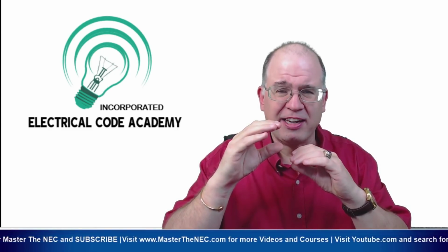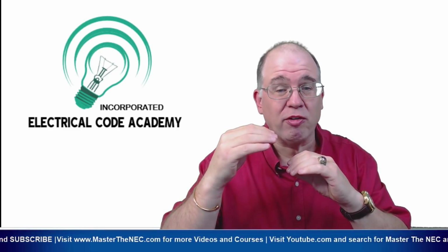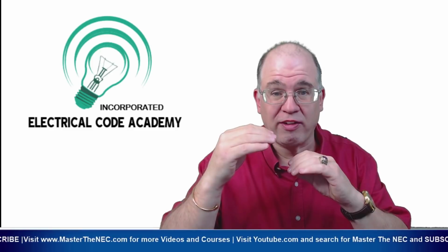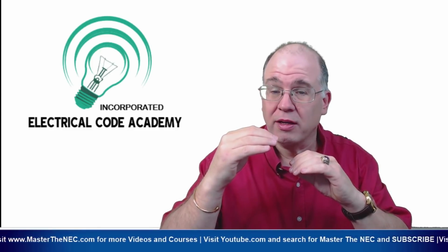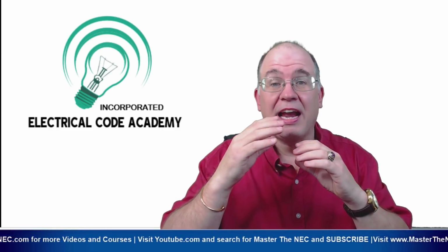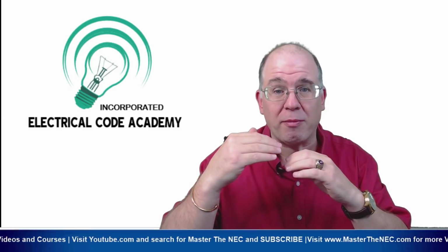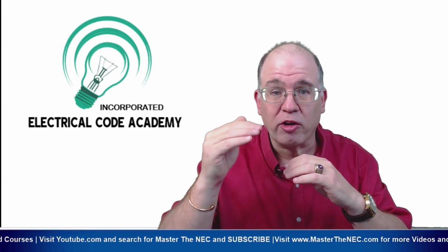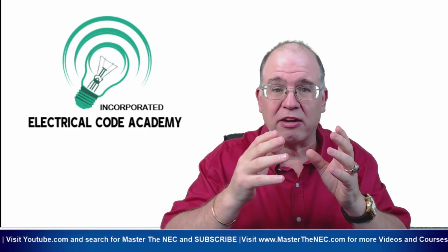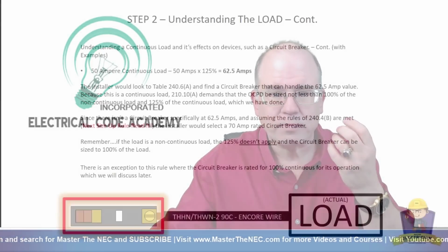Am I protecting that conductor at its ampacity? And the ultimate choice is I got to have an overcurrent device that's at least 125% of the continuous load, but it can't be any less than that. Is it going to protect this conductor? And it might result in me jumping up into a larger size conductor simply because I have to terminate it on this size overcurrent device because of the rules in 210.20a. Okay, so you've got to piece all those things together.